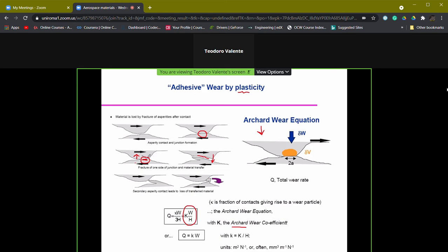plasticity effects. And if we remember, when we have a plasticity effect, that is, when we exceed the tensile yielding strength of the materials, and we can define now the yielding strength because we have essentially confined this phenomenon to metallic alloys, the material undergoes a work hardening phenomenon.